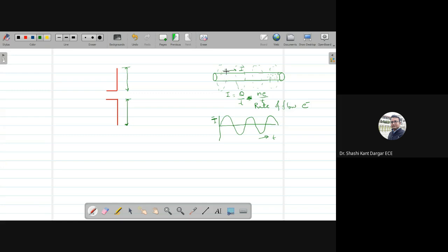Obviously, this will be fluctuating. It keeps on increasing and going down, and the magnetic field also keeps on increasing and going down. So this fluctuation in the field lines happens because of the time varying current. This creates the current standing wave ratio; depending on whatever current is there, there is a current standing wave ratio, and in the direction perpendicular to this we have VSWR, the voltage standing wave ratio. These magnetic field lines are responsible for radiation. So in another sense, we can say current is responsible for radiation. How it propagates, we can talk about separately.